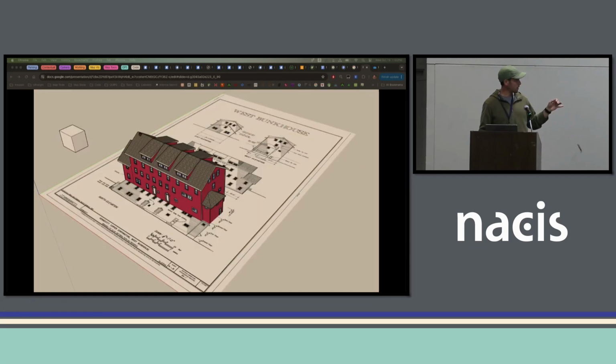So here's a completed model. This is the west bunkhouse where I have all four sides of the building. Everything's drawn, everything's in 3D, even the windows are in there. And I like to do these in their own separate files. Part of the reason I like to do that is I can keep the axes aligned. So I like X, Y, Z to be fit to the corner of a building. Once you get this in the overall model, each building is going to be turned. You can keep the axes contained to the components, but I just think this is easier.